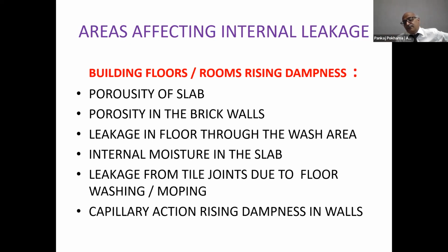Sometimes we see that people are washing the floors with ample water. Even if the area is not a wet area, not a toilet or bathroom, still in their bedroom, if they put a lot of buckets of water, the floor joints are open, and as the tiles are not laid on a concrete bed, the mortar below, which is very porous, absorbs the water and leaks beneath, and that also gives rise to capillary action from the walls, from the junction of floor and walls.